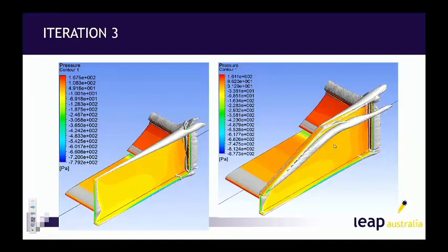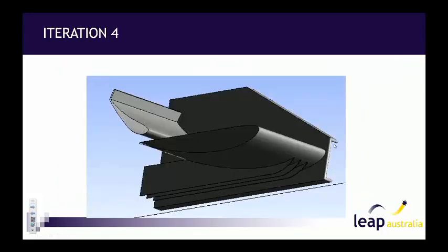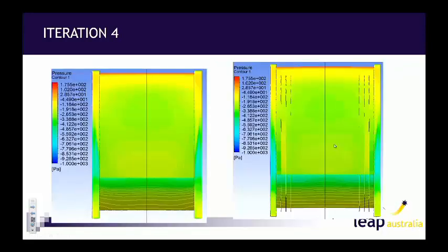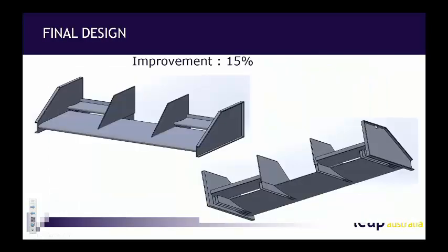The next thing was I did a little bit of literature research, and I saw there were a couple of teams running cut end plates, to improve efficiency in yaw, but they also had some flaps around the top. Looking at that, this is a vortex core, so you can see the vortex that comes off and gets pushed away from the wing. However, that didn't see quite a big increase in gains. So the next thing was looking at something like strakes. Looking at the pressure distribution, the strakes really control the vortices that come off the end plate, and you've got, again, a larger lower pressure distribution against the main element. So overall, there's around a 15 to 20% improvement within the actual design.